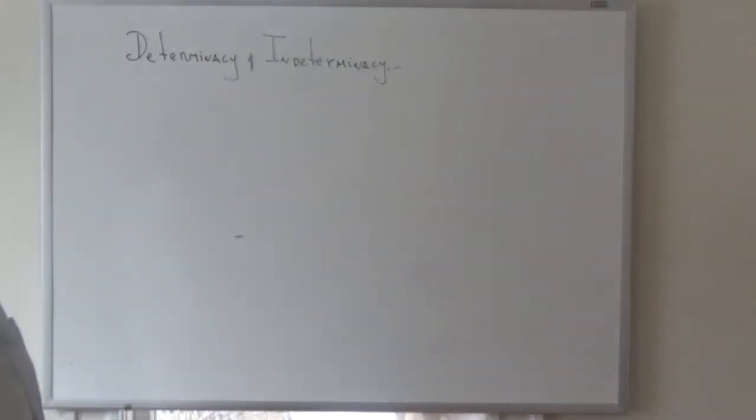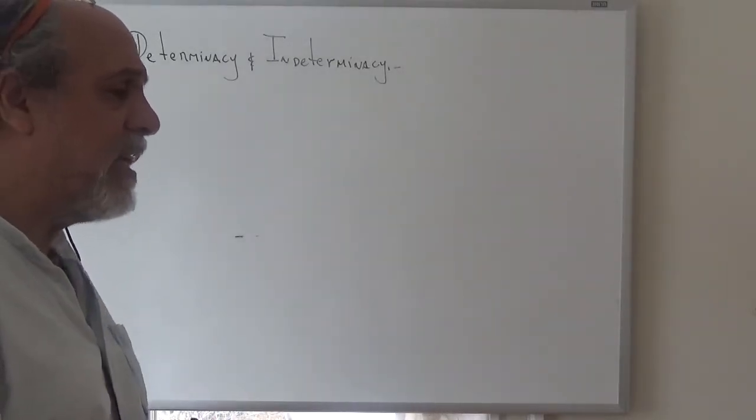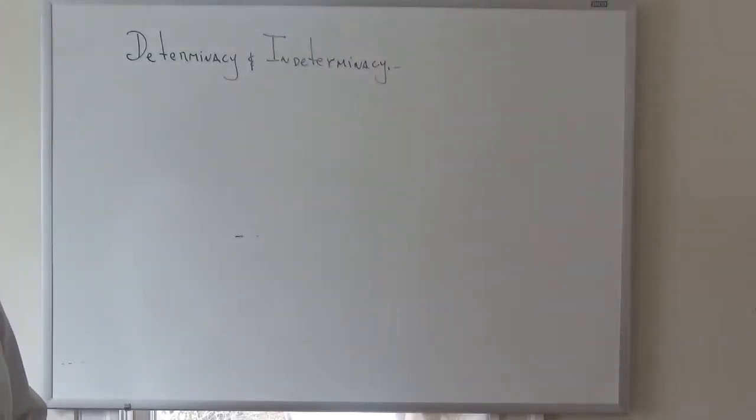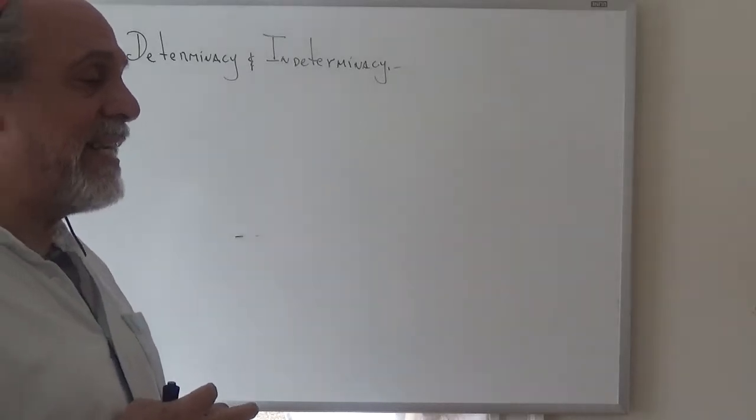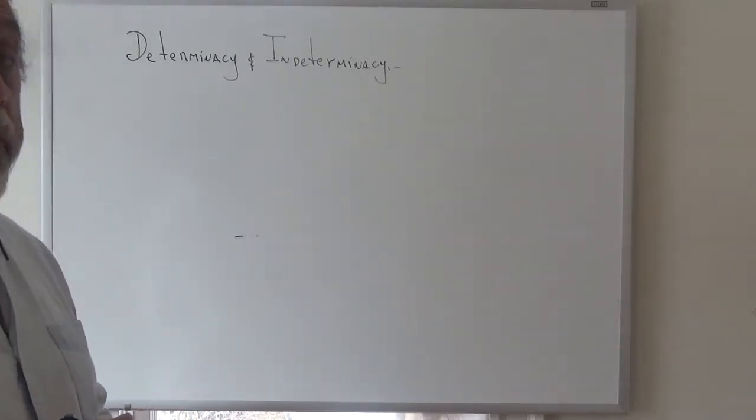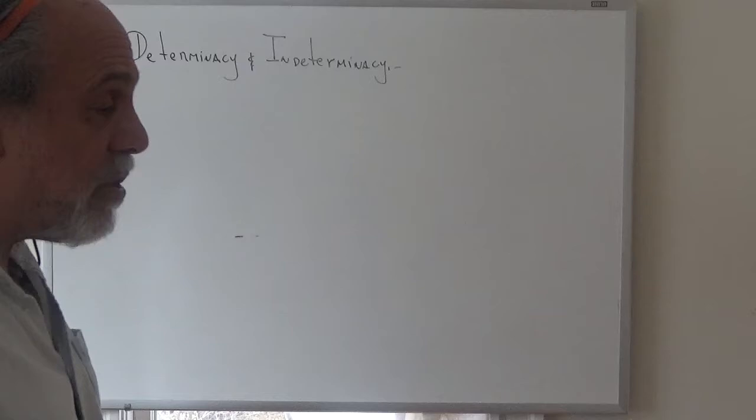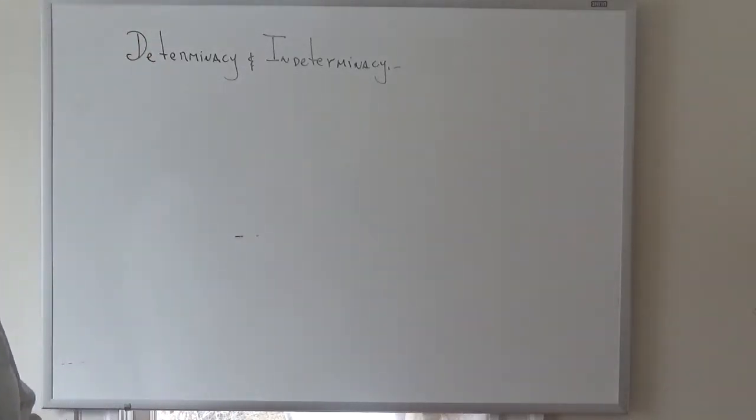If you can calculate whatever you're asked using only statics, that means statics is all that matters as far as that quantity is concerned, and therefore that quantity is statically determinate. If it turns out that statics is insufficient for you to determine the value of the quantity that you were asked, then that quantity is statically indeterminate.